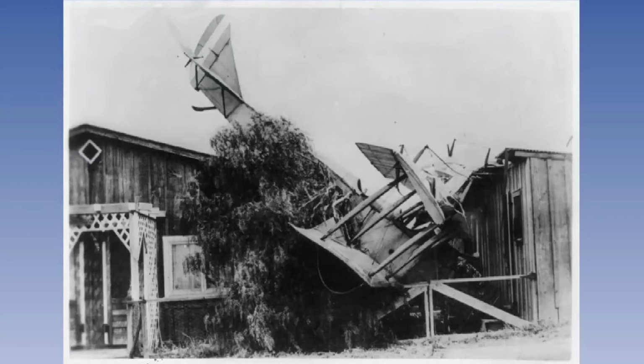This series of lessons will teach you about the many aspects of the stall, an aerodynamic phenomenon which can result in loss of height and ultimately loss of control if not correctly recognized and handled. Such a situation would obviously be potentially very hazardous at low level on the approach or after takeoff. It is vital, therefore, that a pilot should be able to identify the signs and symptoms of stalls in any configuration or stage of flight, in order to prevent or recover from a stall with minimum height loss.